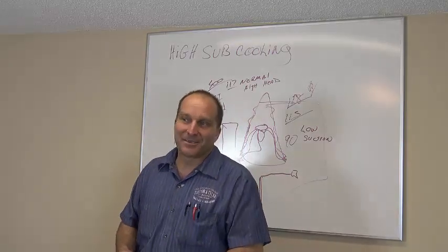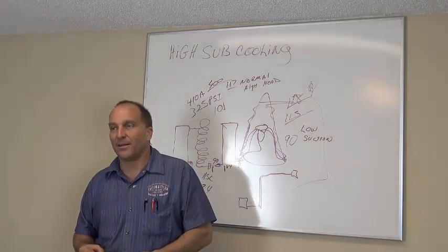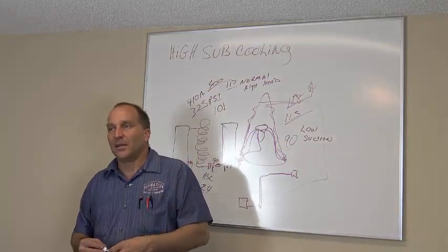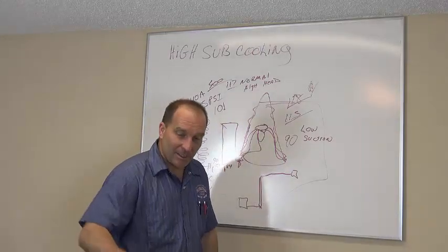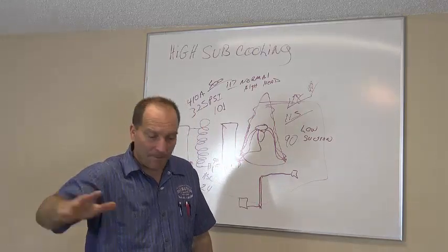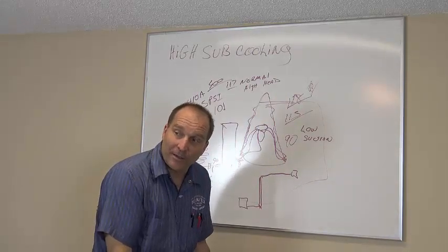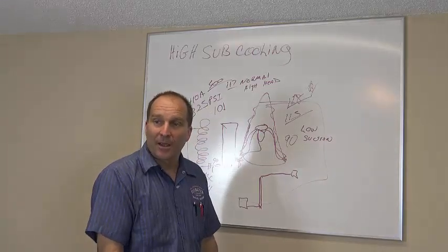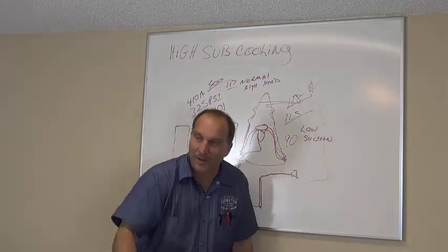Perception. That's right. It's the first thing they're going to see. Right. Okay, and that's happened many a times. Customers calling up because of that. Your guy was supposed to clean it. Or how about this? You take the cover off of the Rheem system, you got the compressor sitting in the electrical compartment right here, right? Well, that part of the condenser coil gets filthy, filthy dirty right there, right? You got to clean that really good. What about at the bottom of it? Well, you got to clean that too, and you got to hose all that stuff out.